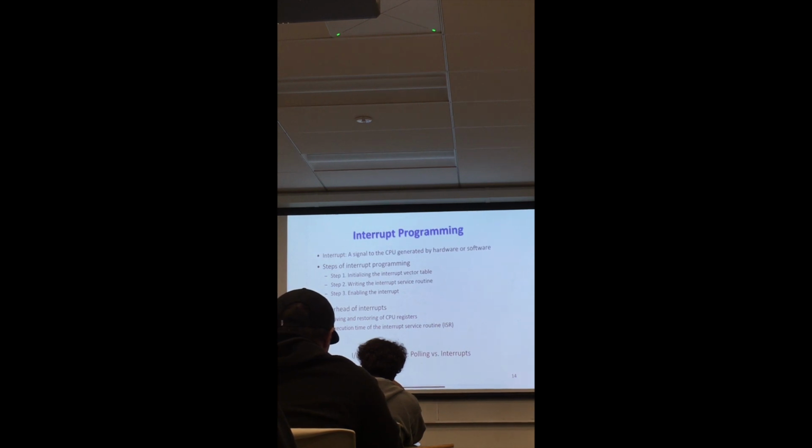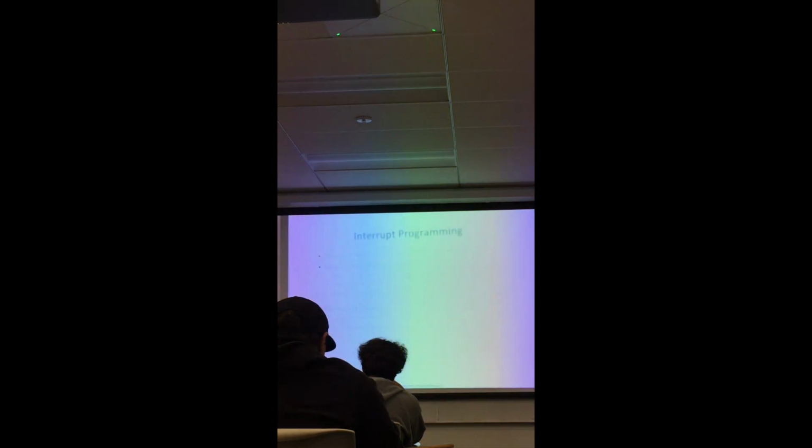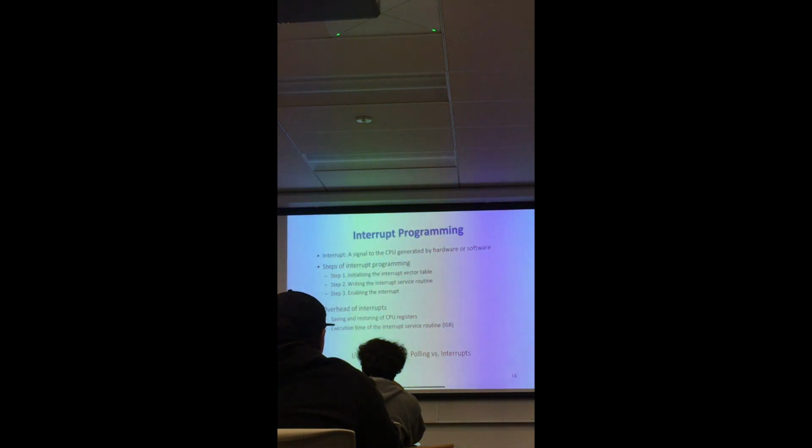So for example, you read an instruction which doesn't exist and the CPU doesn't know how to interpret it. That would be an exception. It reads the instruction, but it cannot execute it: blue screen. But you can capture that. Contemporary microcontrollers can actually capture that event and it will trigger an event. If you don't process it, it will be a blue screen. But the fact is that this can generate an interrupt which you can process. So that will be a software interrupt. This is the type of question I make: you brought me an example of a software interrupt, what was the requirement for software to process it?